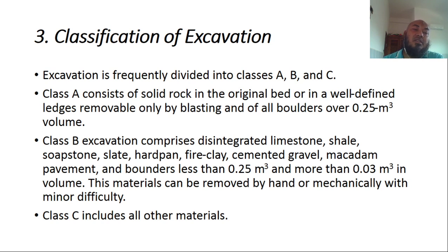Class B is excavation comprised of disintegrated limestone, shale, soapstone, slate, hardpan, fire clay, cemented gravel, macadam pavement, and boulders less than 0.25 cubic meter and more than 0.03 cubic meter in volume.